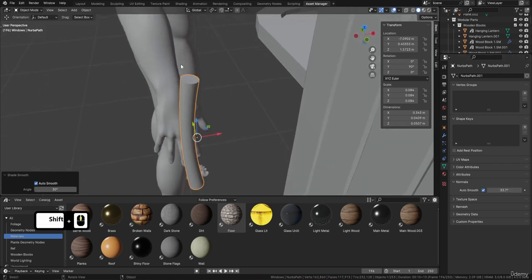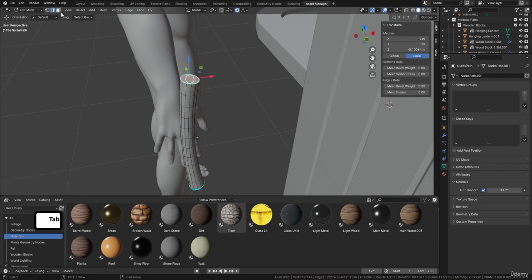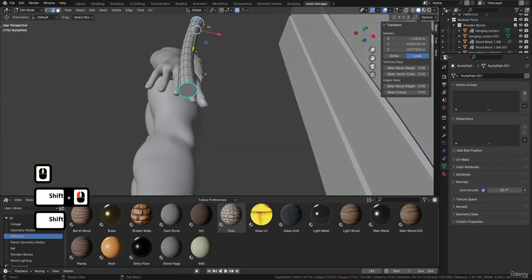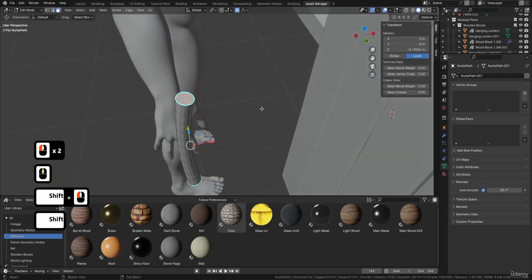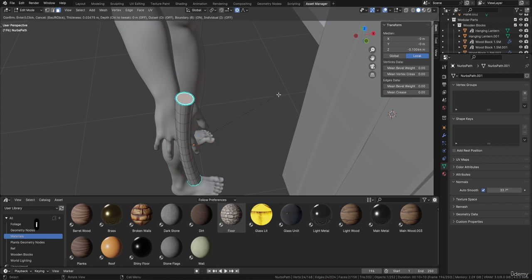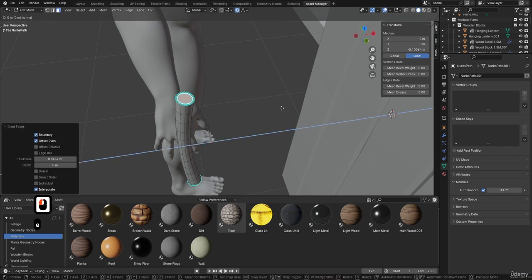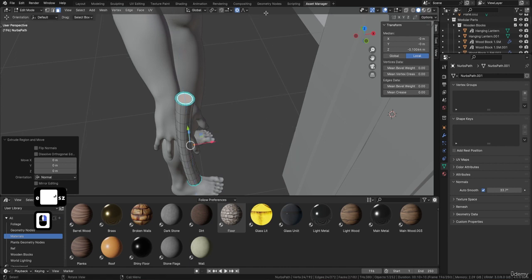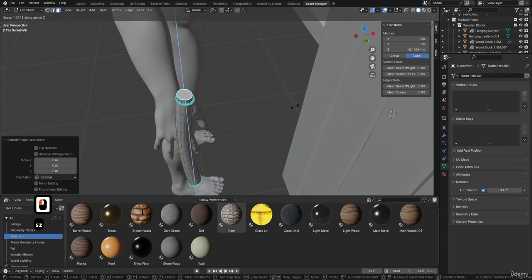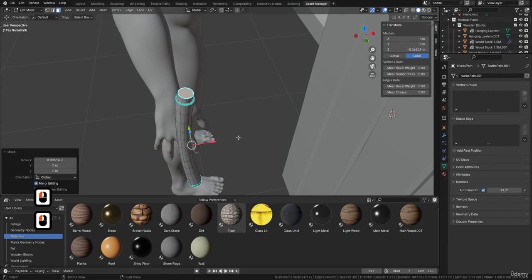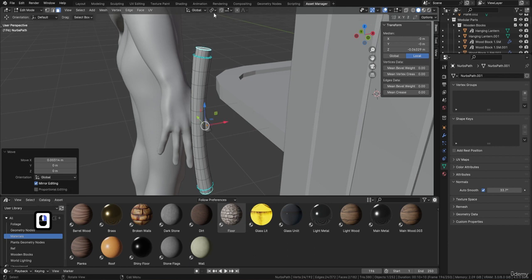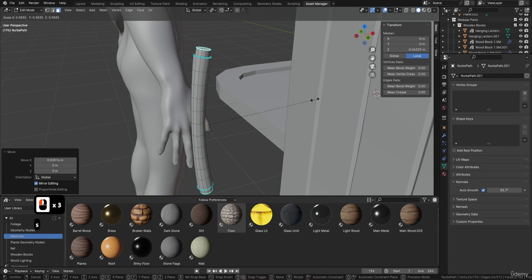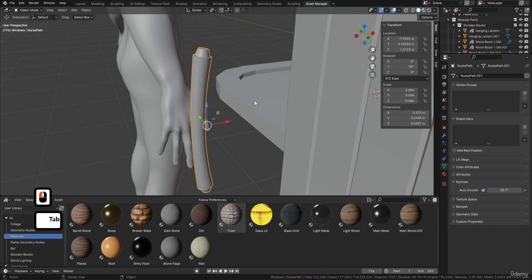All right, so now what I want to do is bring up these parts. So I'm going to make sure I'm on face select, grab both of these. So this one here, face select, this one, and this one. And then what I'm going to do is insert, so I, insert, and then E, enter, S, Z, pull it out. But make sure proportional editing is not on. So S and Z, pull it out, and then pull them over to the side like so. And finally, I'm just going to press Alt S. Yeah, I can't press Alt S, so what I'll do is come up, put it onto individual origins, and S, and then I can actually make it smaller like so.